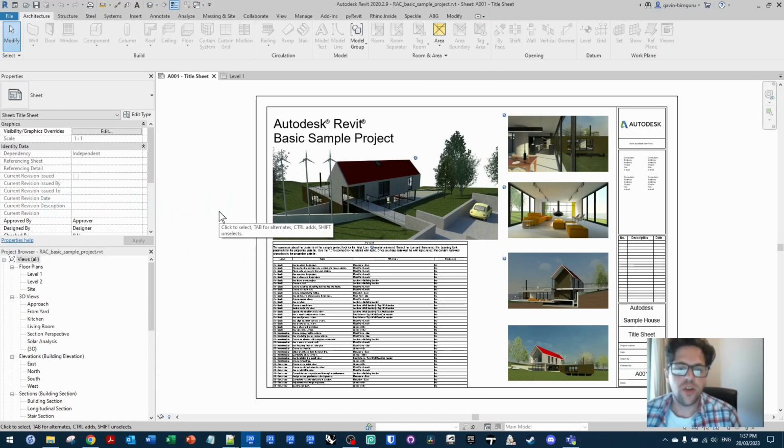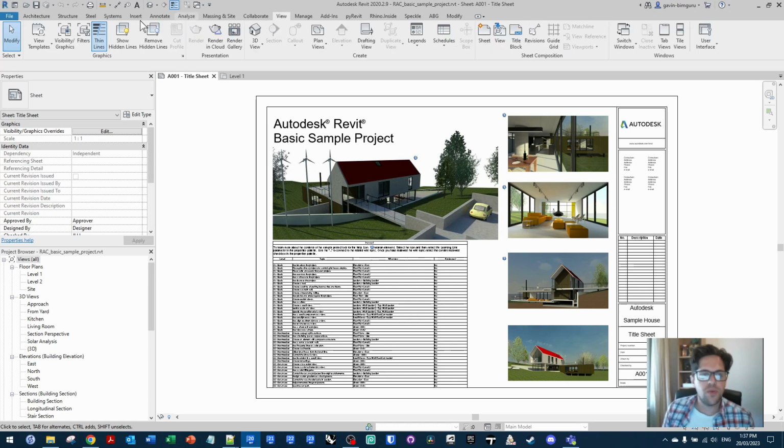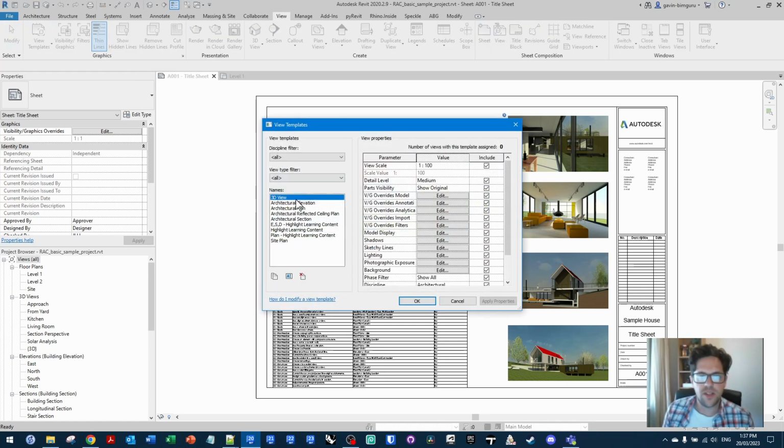So today we're going to be solving a pretty common problem that especially model managers and BIM managers may face, and that is when transferring project standards between models, you have to transfer everything effectively, rather than very specific things. And some things are very difficult to copy, such as, not just copying and pasting between models, but you sometimes can't even select the objects to copy them. For example, view templates. So let's say, for example, in this model here, I have a whole set of view templates available, and I want to move across a couple of the plan or section-based view templates.